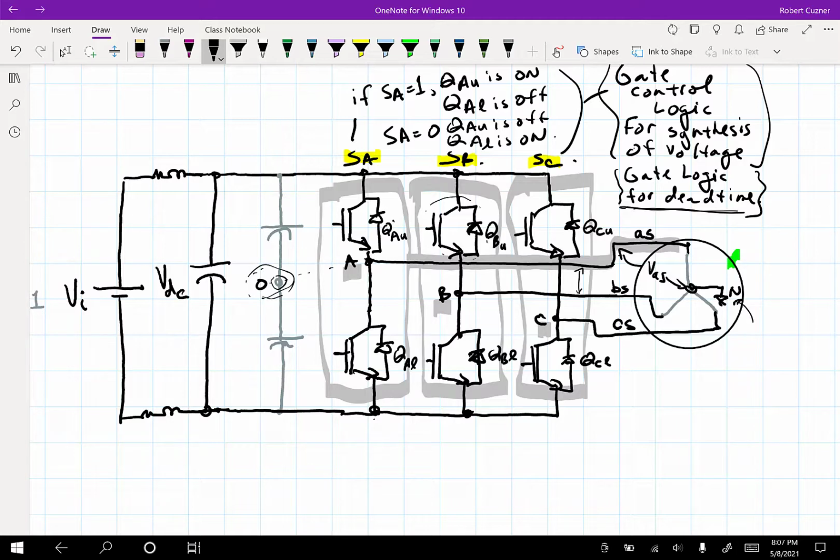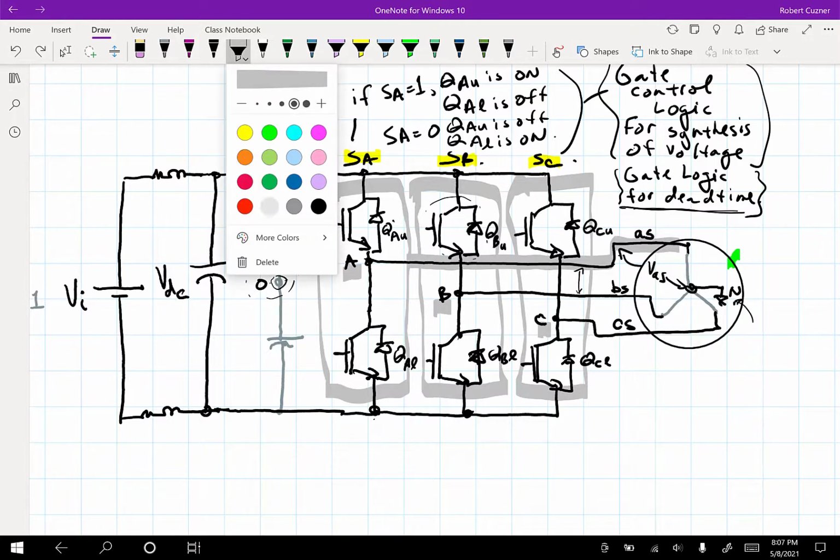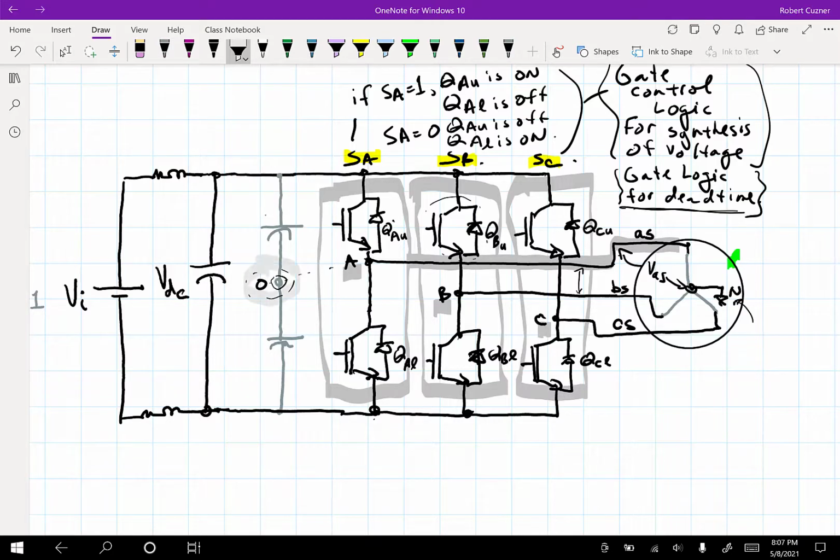This may not physically exist, but the circuit is symmetrically laid out, so it's going to behave as if this node does exist. I'm sorry, I'm getting a little crazy with the gray. So it will behave as if that does exist, even though it's a virtual point, in the same way that everything is going to behave as if that point exists. It's really a kind of symmetry that occurs in any electrical circuit. We don't really think about it in DC circuits.